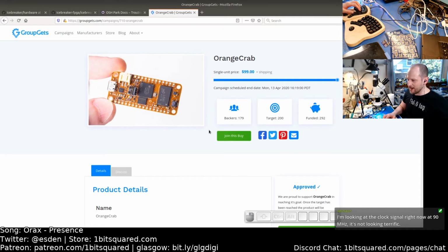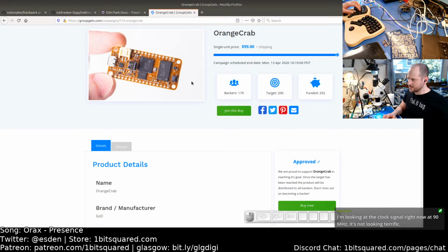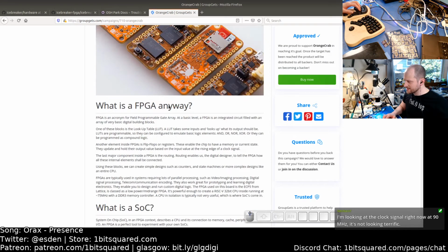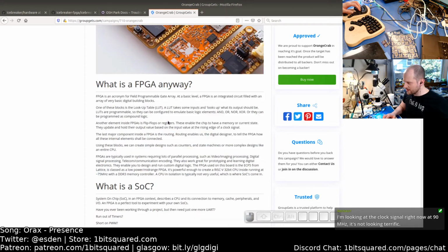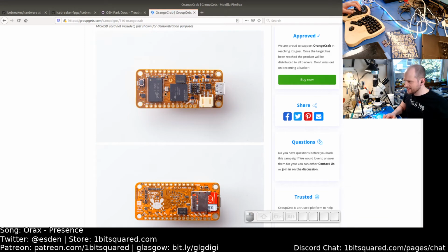So anyways, this is Orange Crab. It's an ECP5 FPGA development board with DDR3 RAM attached to it. There's no HyperRAM on here, I think; this is the flash. It's in the Adafruit Feather form factor. And you see the squiggly lines here? This is Greg doing some magical stuff to length match, and he wrote a script that is very useful for length matching. Yeah, nice squigglies, as we say in the trade.